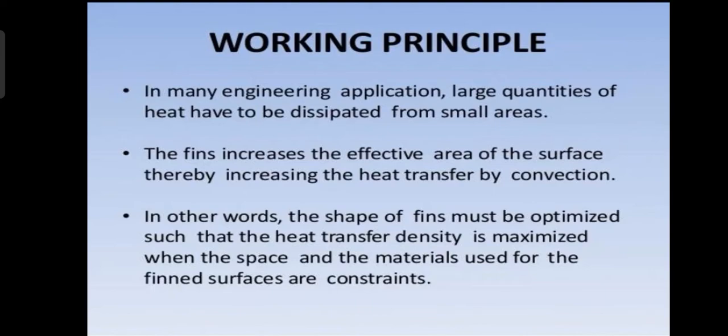The working principle: in many engineering applications, large quantities of heat have to be dissipated from small areas. Generally, the fins increase the effective area of the surface, thereby increasing the heat transfer by convection. In other words, the shape of the fins must be optimized such that the heat transfer density is maximized when the space and the materials used for the finned surfaces are constraints.